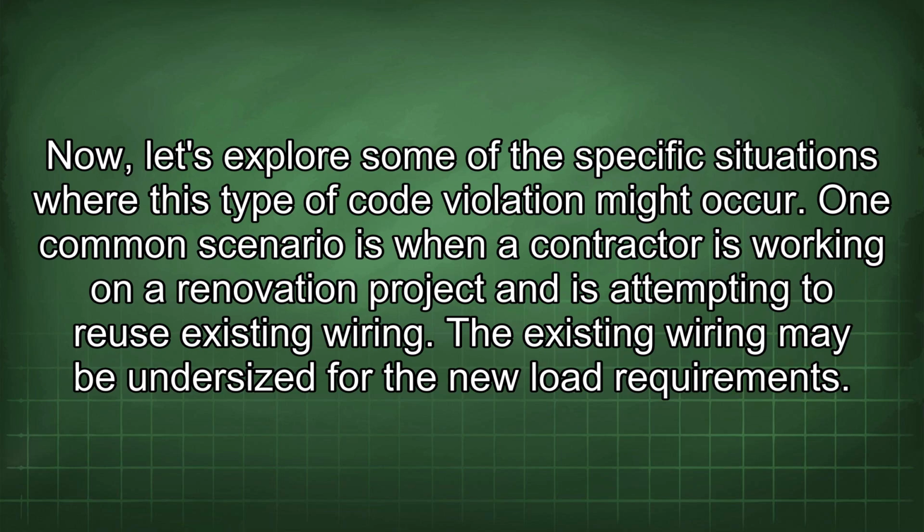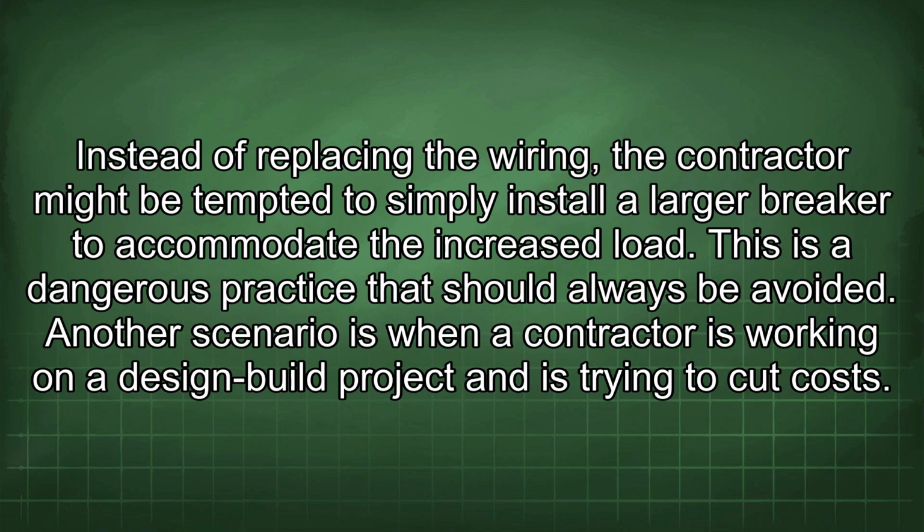One common scenario is when a contractor is working on a renovation project and is attempting to reuse existing wiring. The existing wiring may be undersized for the new load requirements. Instead of replacing the wiring, the contractor might be tempted to simply install a larger breaker to accommodate the increased load. This is a dangerous practice that should always be avoided.